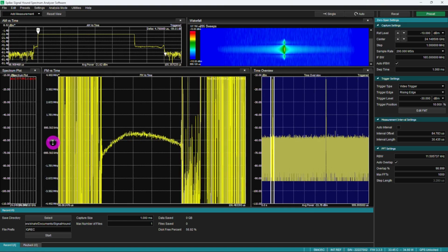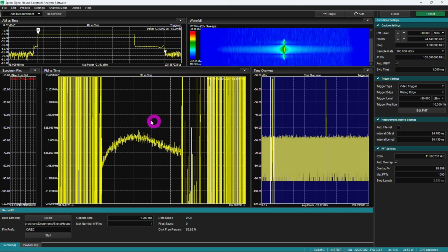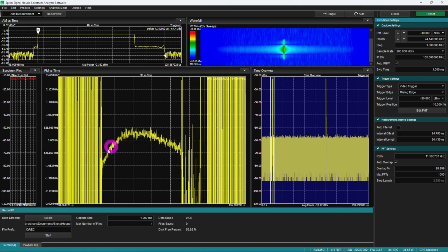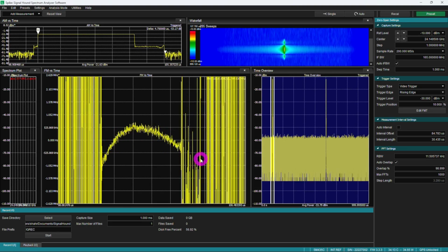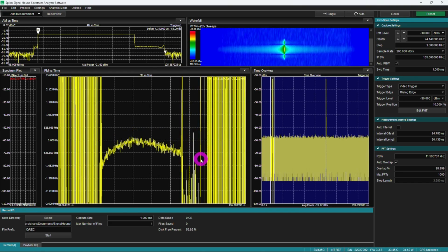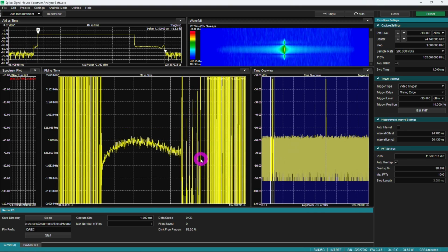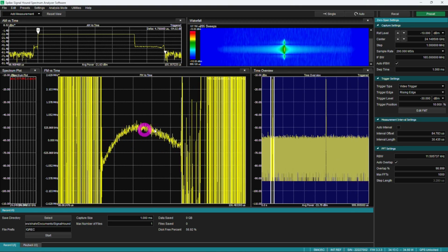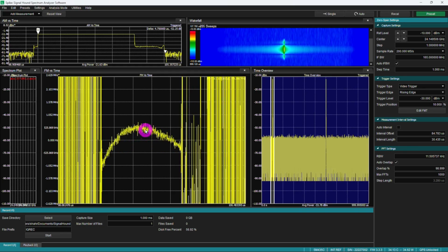And if I look in the middle, you can see what happens during the transmission of that pulse. Now, during that transmission, the frequency does change a little bit. That's changing by about a couple of 100 kilohertz. Now, for a short-range radar like this one, this probably doesn't matter anyway, because it's not going to affect the FFT being taken. It's not going to affect the Doppler radar because the range is so small. But nonetheless, you can see that indeed there is a little bit of frequency variation while this pulse is happening.